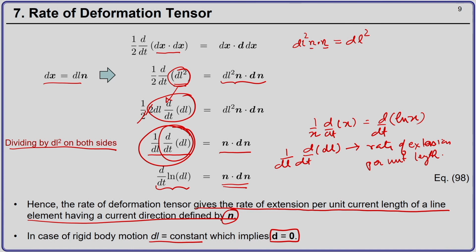So, this has a physical implication: under rigid body motions the body will not generate any strain. If there are no strains generated, there will be no stresses generated. This is physically intuitive, because if you just rotate a body, there will not be any stresses generated inside the body. So, if you have a strain rate measure, for example D, which gives you no change in the strain if there is a rigid body motion, then you will physically get no stress. If you derive your stress from D, you will get no increment in the stress, which is physically possible.